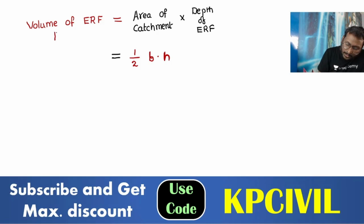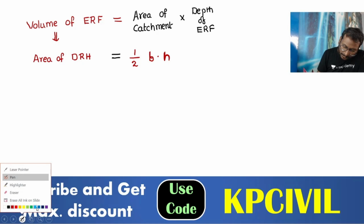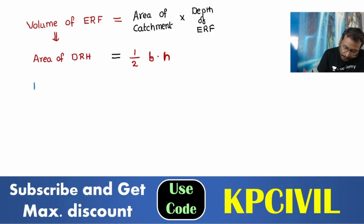Because volume of effective rainfall is equal to the area of the direct runoff hydrograph, DRH, half into base into height. So now I am equalizing: half into base, where base is the time base and height is the peak discharge.